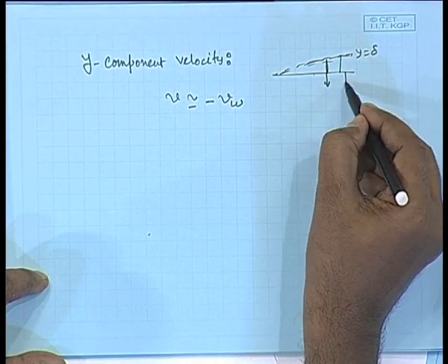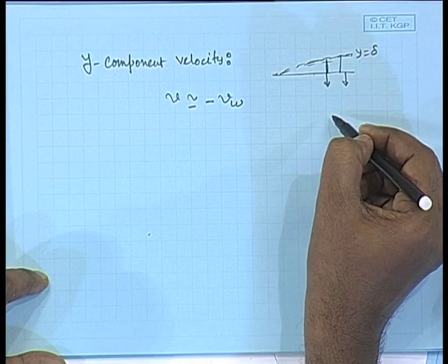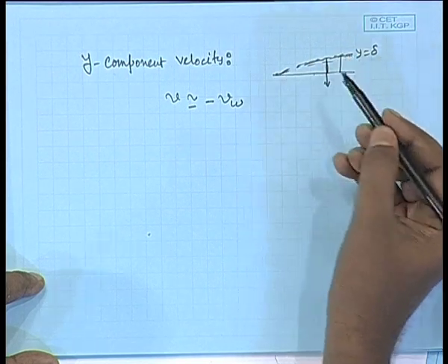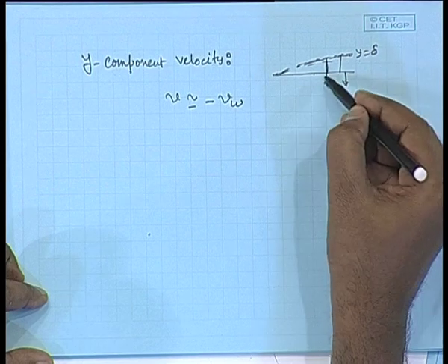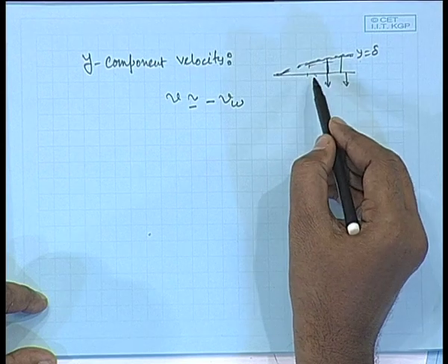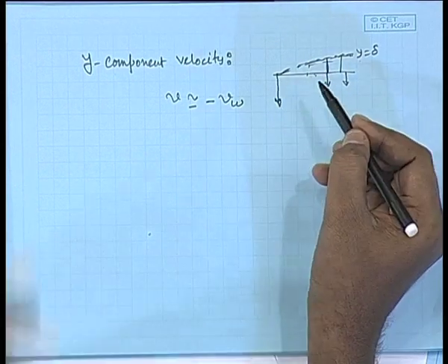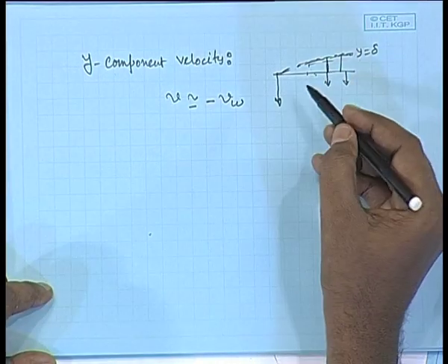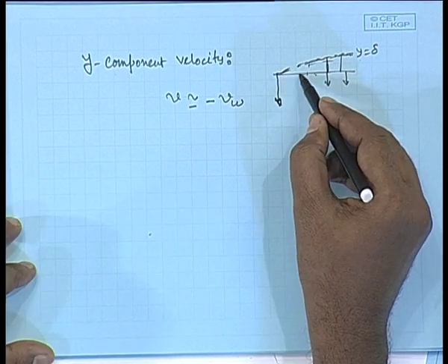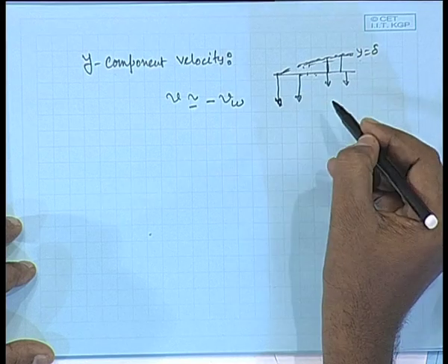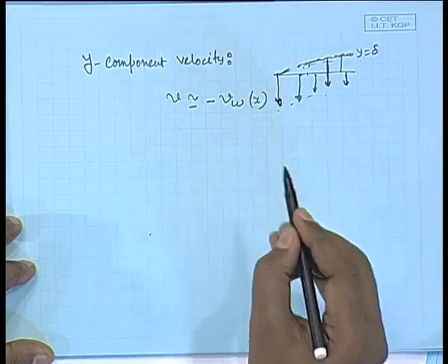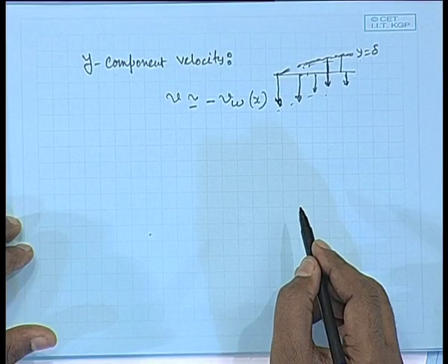Okay. V w is the measurable flux that you are getting out of the membrane surface, and since we said earlier this is increasing as a function of x, the resistance against the water flow rate towards the membrane will be varying. The more this thickness, the less will be the flux. So, flux, or permeate velocity, whichever way, because it has a unit of velocity, will be maximum here, because this thickness is minimum there. Then as the thickness increases, the permeate velocity is decreasing. So, it will be a function of x.